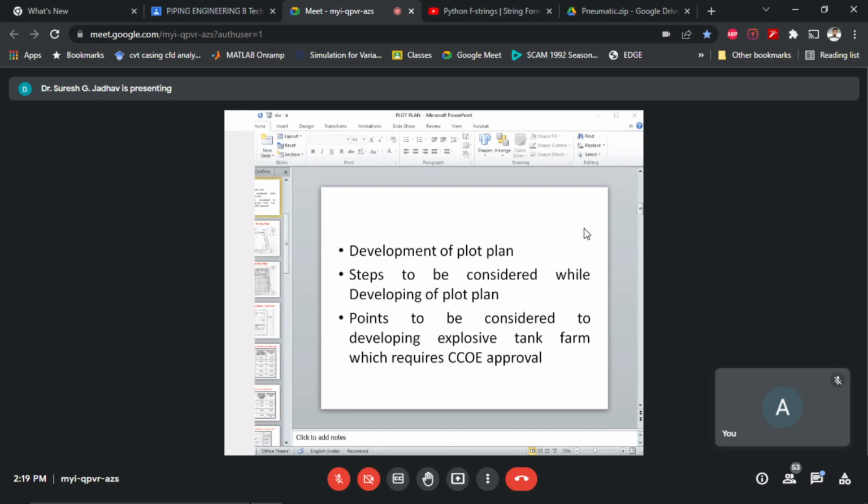Enclosure capacity shall be calculated after deducting the volume of the tanks other than the largest tank to the height of enclosure. A freeboard of 200 millimeters shall be considered in fixing the height of the dike.